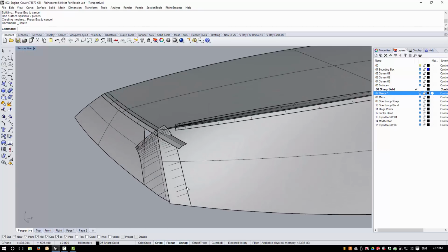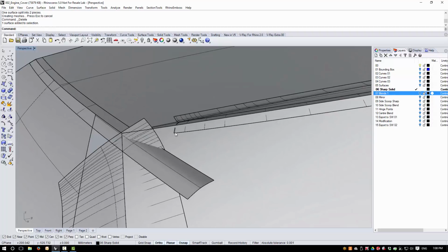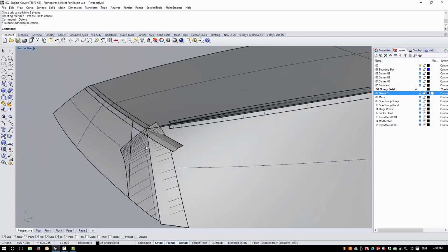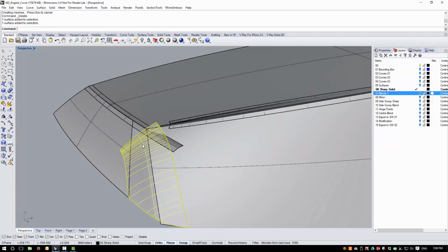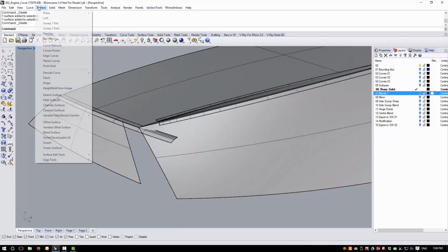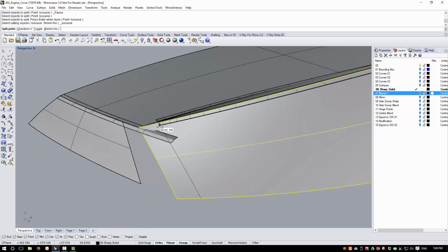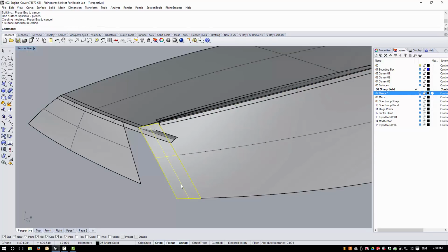Now, the blend edge on the side surface wants to run up to this point here on the smaller blend. So this blend here now is redundant, and I can again use split at isocurve, make sure that I enable the shrink option and snap to this edge, and then delete.